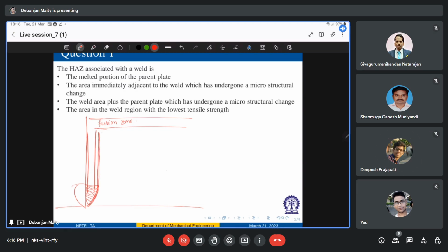So some boundary will be there, which will be your fusion line, right? And then there will be some fine grain heat affected zone, and depending on your cooling rate, there will be distinct zones in your heat affected zone, right? So the actual cooling rate with which the weld cools, the composition of base metal, and whatever flux you are using, those things decide the overall microstructure of the weld, if you are thinking of this iron carbon, during transformation of austenite to ferrite, right?